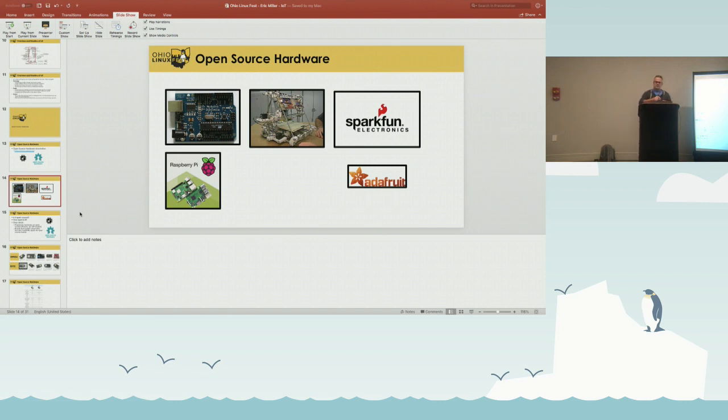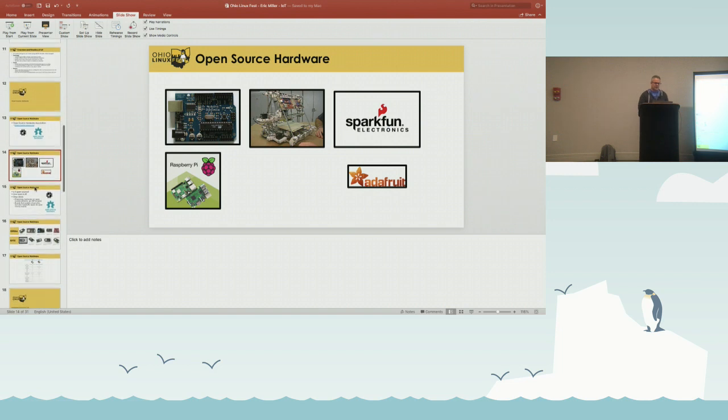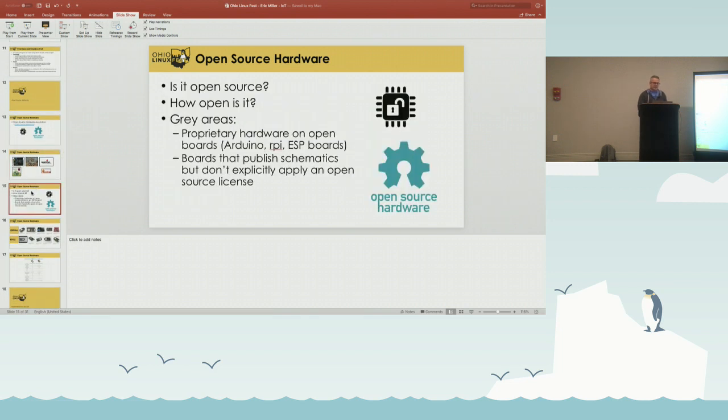What a developer will do is take that platform if it's suitable, and they'll breadboard around it and get it working, and then they'll take the schematic that they have, because it's open source, they'll rip out the parts that they don't need, they'll add the parts that they do need, have an electrical engineer do that, and then they'll send off Eagle files to a PCB fab place, and then they'll have their thing come back that might have the same chip, power supply, and USB serial as an Arduino or a Raspberry Pi, but then it has other stuff on it that they added for their solution, right? So that's why this is really important, and why companies like SparkFun and Adafruit are really cool.